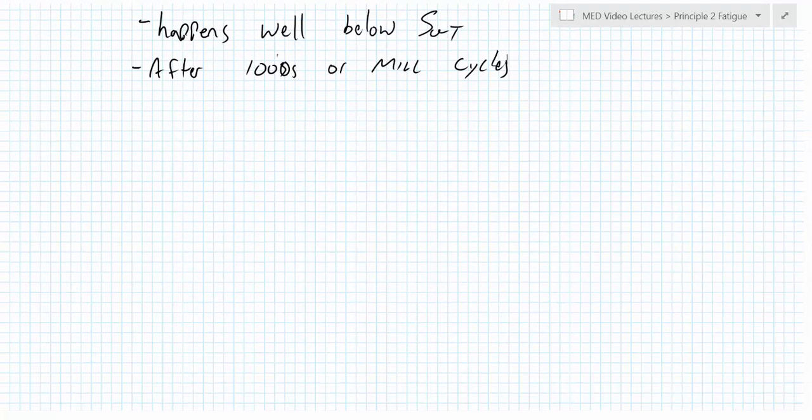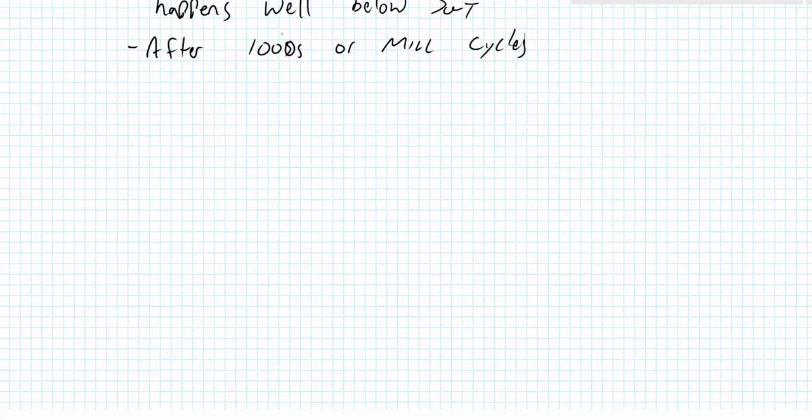Just like static failure analysis, we have theories of how things break. The reason we have theories for fatigue failure is that there is no repeatable scientific law that governs the probabilistic behavior of how cracks grow. When we get down to the very minute level and we're looking at whether or not a crack will form at a particular location, the arrangement of those atoms and the probabilistic nature of our universe mean that there's no way to deterministically and absolutely say, yes, a failure will occur here. All we can do is say, based on high probabilities and over a certain period of time where those probabilities exist, that there is a likelihood of failure. So we have what are called fatigue failure theories.